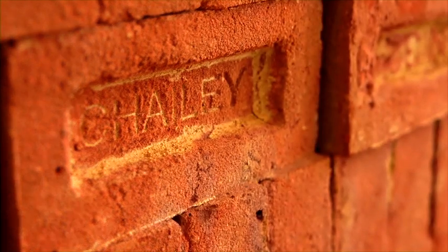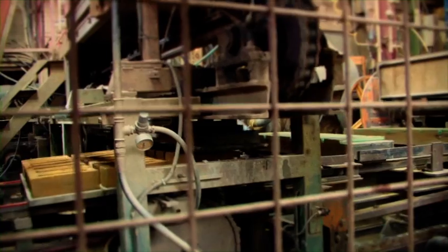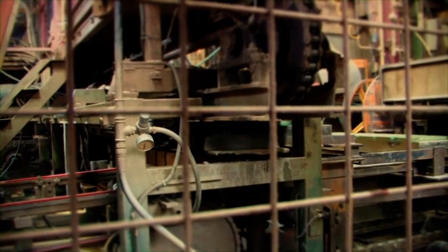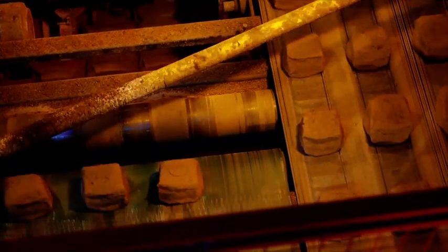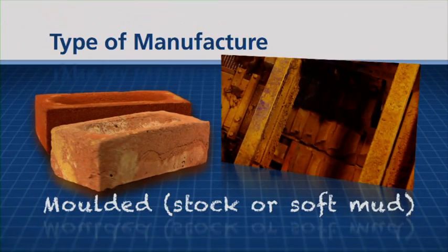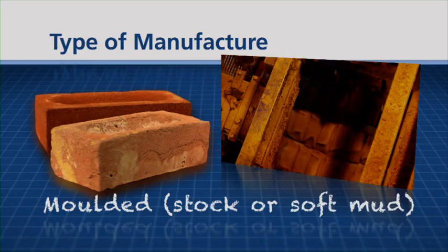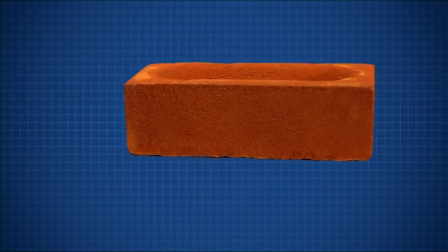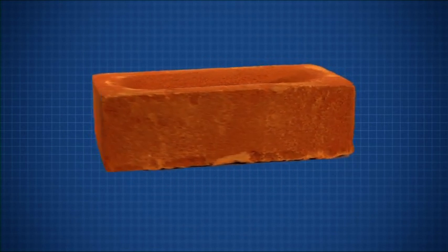Another process which gives a similar texture to that of a handmade brick is simulated handmade. Here, a machine throws the clay into the moulds instead of being hand-thrown. As these processes result in very similar textures, consideration must be given to whether the brickwork being identified is either handmade or machine-made. The most common and widely used method of production is machine moulded. The resulting appearance of these bricks is flatter and sanded with minimal creasing.